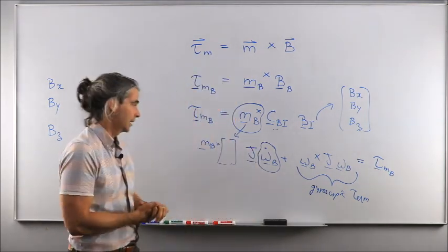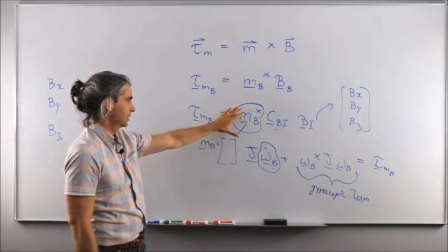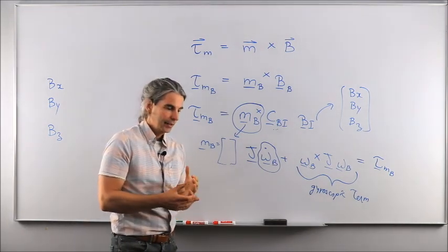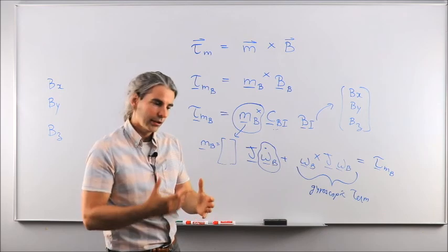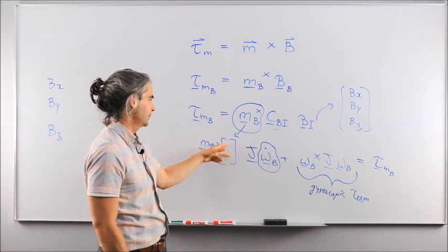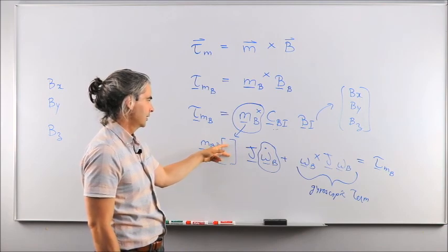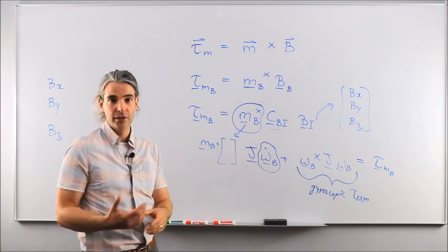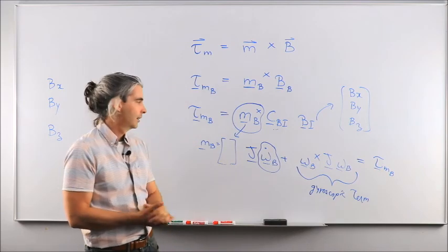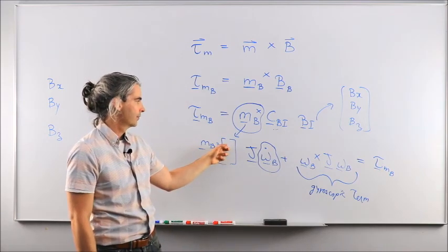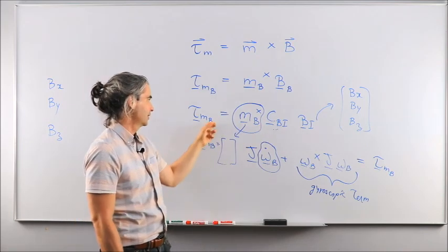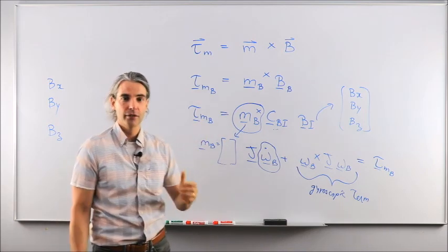Okay, it's not up to you to determine that because this is a highly complex scenario where everything has to be modeled in terms of electronic components and capacitor and inductance and current inside the spacecraft. So for you, this is really a hands-off process. Take that as being given to you, similarly to the inertia matrix of the spacecraft given to you by the structural engineers, or the mass of the spacecraft given to you by structural engineers as well. So that will always be provided to you. This is not your business, okay? But your job is to use it in that equation to figure out the magnetic torque impacting the spacecraft motion.